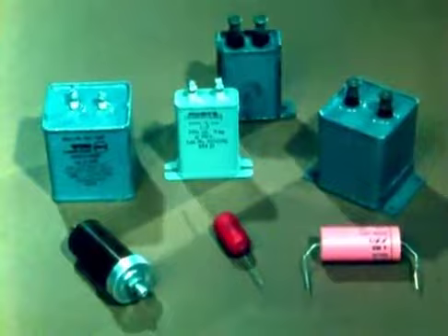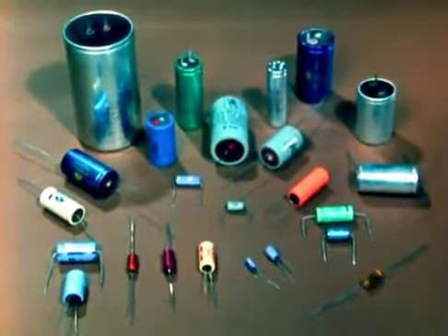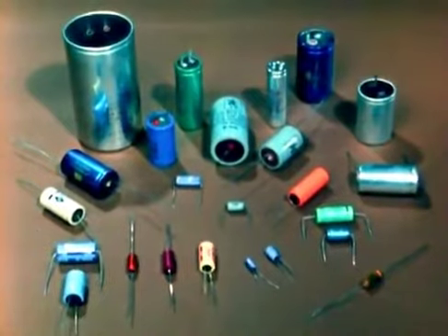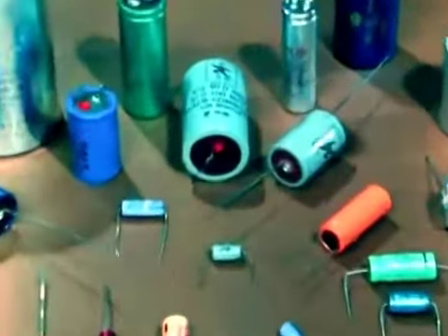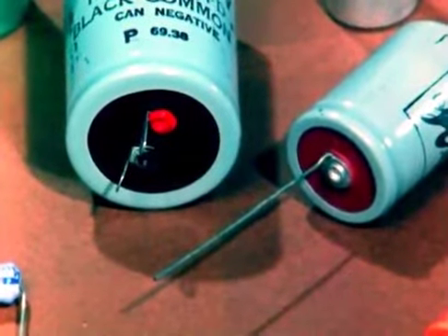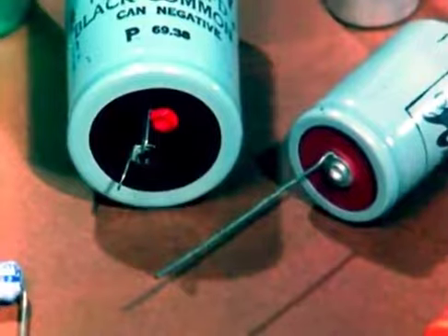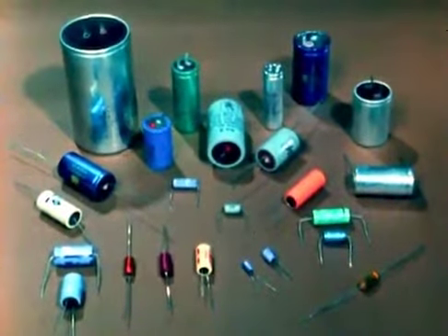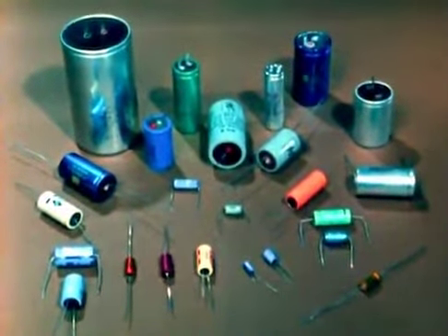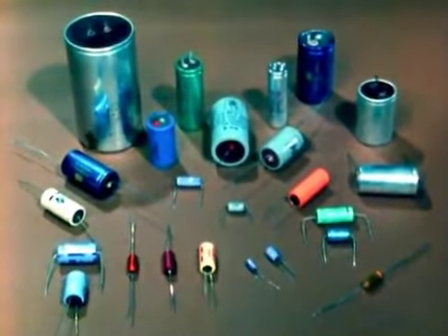When paper capacitors become inconveniently large, electrolytic capacitors are used. Here the dielectric is a thin film of oxide on one plate. The capacitor must be connected with the terminal with the red end or spot to the positive side of a DC supply. As with the paper capacitors, there's a great range of shapes and sizes of electrolytic capacitors.